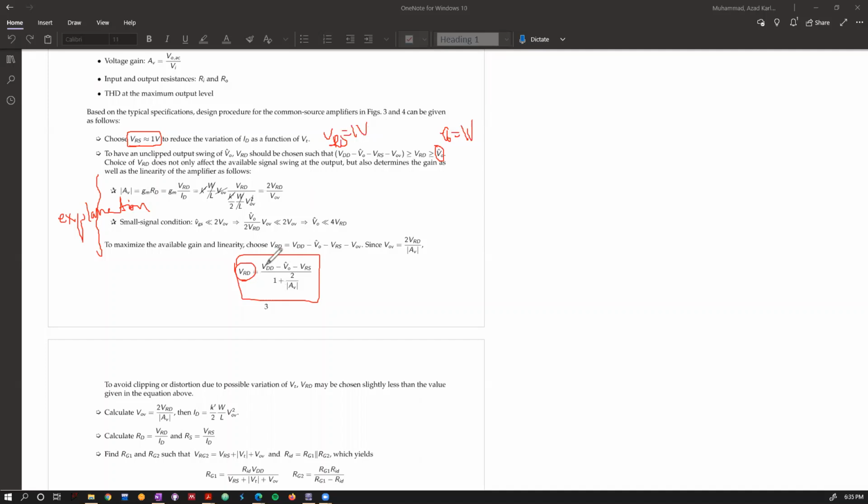But let's see, you know your VDD, which is 5 volts. V naught hat is chosen here. VRS is chosen here. The gain, 25, is given in the lab manual. So you know all of these values, you can find VRD. So by the end of this step, you'll have your VRS, you'll have V naught hat, and you'll have VRD. Any questions on just these two steps? All right. So once you have these values, now we move on to the next step.